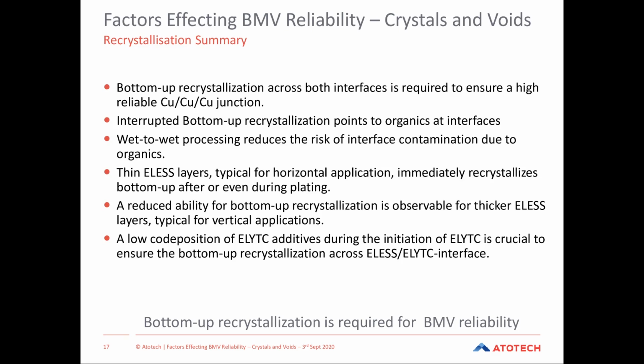Moving out of the electrolysis layer a little bit, we also have to be aware that the electrolytic baths can have an impact on crystallization as well. They are also prone to additive co-deposition, which can pin crystallization to the edge or within the electrolysis layer itself as well. So it's pretty critical in determining where the crystallization boundaries occur when you have them, because it's going to indicate potentially where in your process and your production routes we have to start looking in terms of troubleshooting. Okay, so relatively simple subject in terms of crystallization, but there's a lot of complex things potentially going on within that itself.